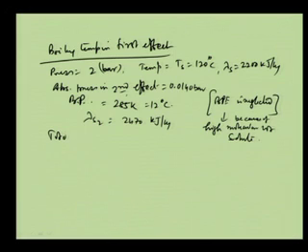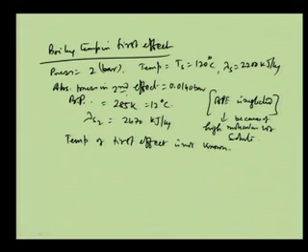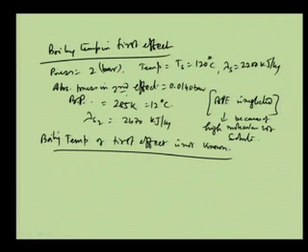Now, the total temperature drop. What I do not know is the temperature of the first effect, which is to be calculated as the boiling temperature. So, what we need to know is delta T equal to delta T1 plus delta T2 as we have seen, and that will be equal to T s minus T2, and the boiling point elevation is equal to 0. So, this happens to be 108 degree centigrade.